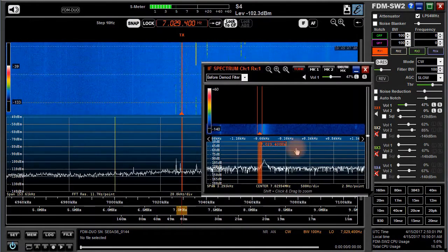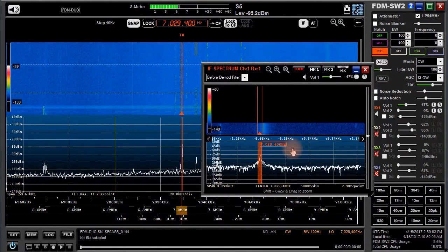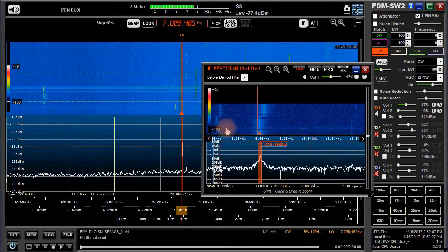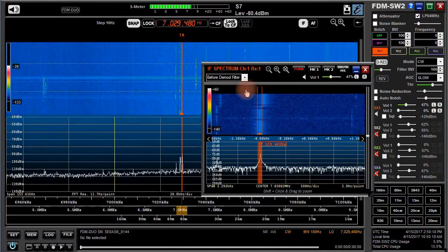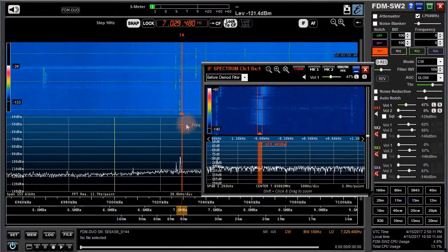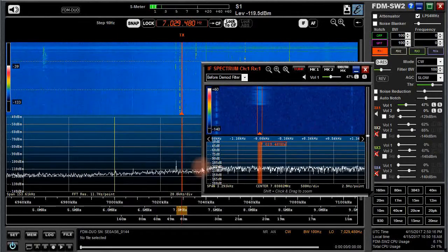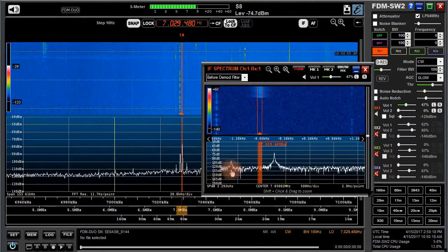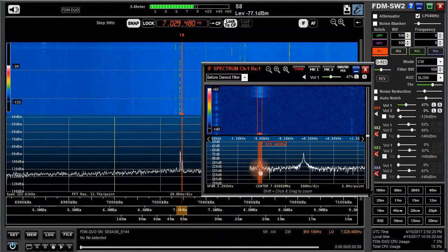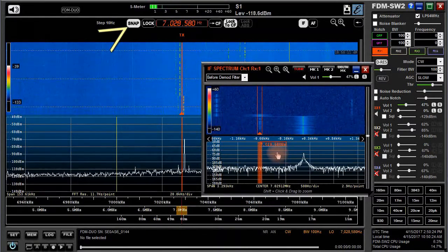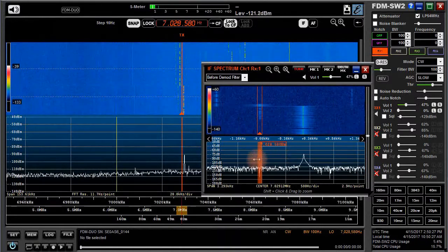Using the main display for rough tuning and finer tuning with the IF spectrum gets you really close. A little fine tuning using the knob with a tuning step of 10 Hz or less gets you right on. For CW, I already have the tuning step at 10 Hz in the software. If you want it finer than that with the knob, be sure to turn snap off in the software. If this is a little confusing, review Part 2.